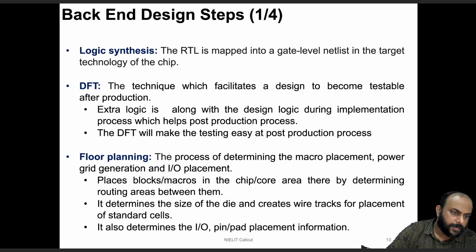So after DFT insertion is done, typically the next step is floor planning. Floor planning is an iterative process which does a few things. It determines the macro placement, the power grid generation, and IO placement. Macro placement means the logical placement of where things should be placed on your die. It's just like we are building a house. We need to first decide where should be the bedroom, where should be the dining room, where should be the family living room, where should be the kitchen, and so on.